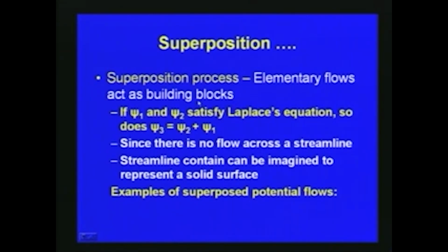So, this is the basic principle of superposition. Since there is no flow across a streamline, the streamlines can be imagined to represent a solid surface. Once the Laplace equation is satisfied by two stream functions, their combination, whether adding or deducting, also satisfies the Laplace equation. That is the basic principle upon which we do the superposition process.